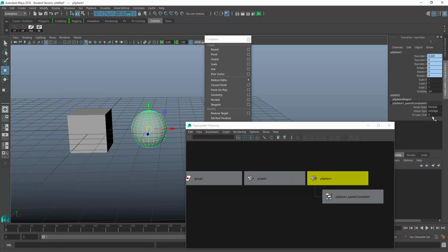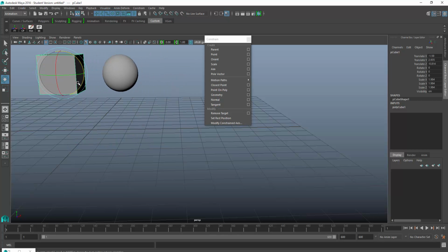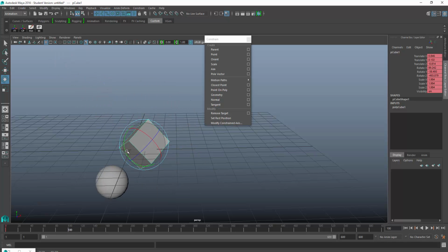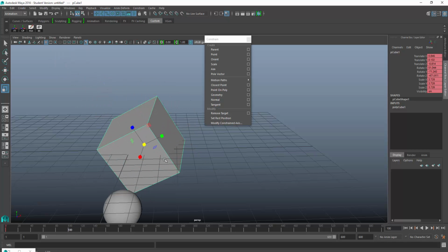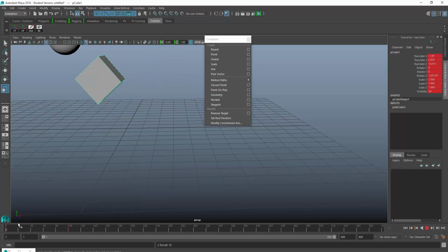So in terms of animation, we can set it up so that this starts out at 1 for the parent, and we can say, okay, it's going to be keyed at 1, so we could just right click and say key. You can select your cube, move it around wherever you want, rotate it, and hit S so that you can key that where you want, then maybe go to another frame, position it, rotate it, scale it, and hit S to key that. So now you have this kind of thing happening here.